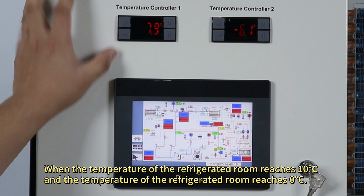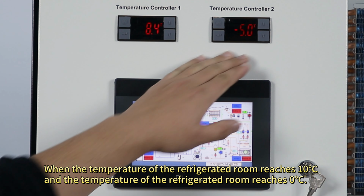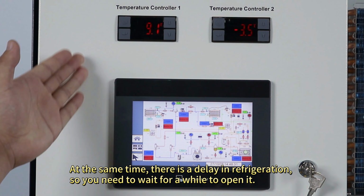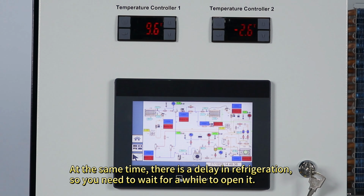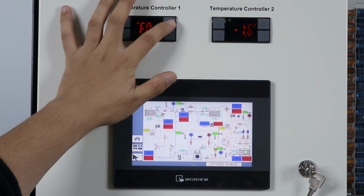When the temperature of the refrigerated room reaches 10 degrees centigrade, and the temperature of the frozen room reaches 0 degrees centigrade, the two solenoid valves can be opened. At the same time, there is a delay in refrigeration, so you need to wait a while to open it. Now adjust the temperature back to the initial setting.